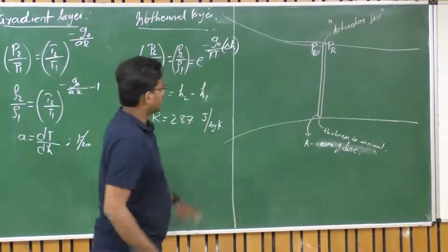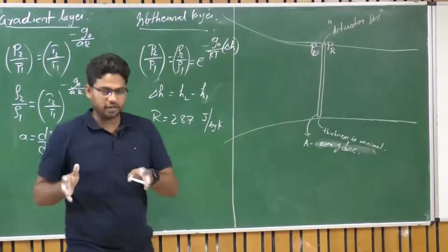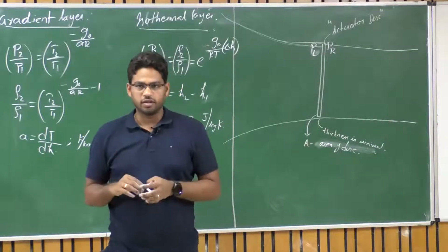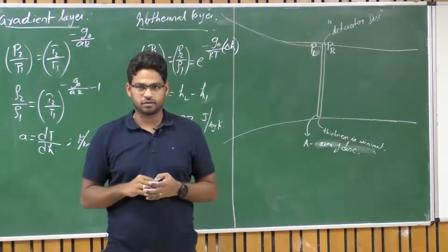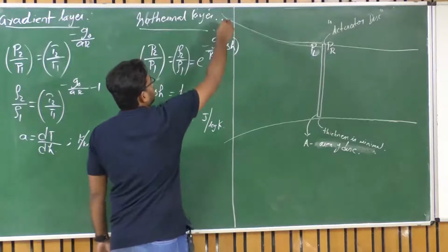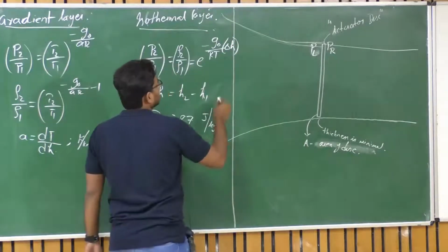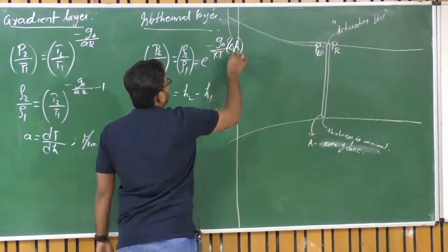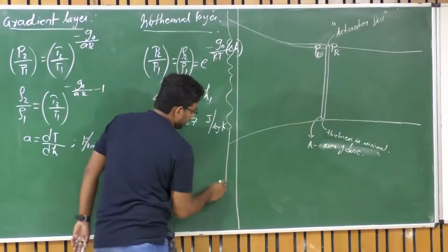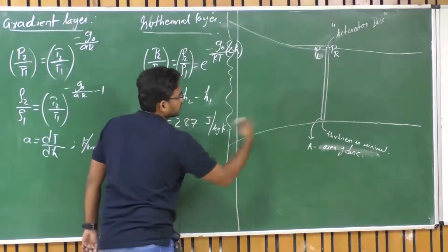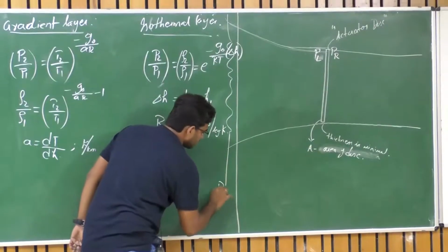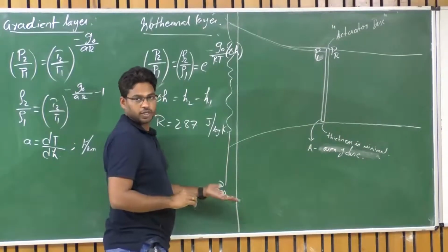So let's now first look at far ahead. Let us say if I place a fan here, somebody who is sitting 100 meters from here, is he going to feel any difference because of this? Definitely no, most likely no, with the ordinary fan that we generally use. So at far ahead, which we call the upstream of this disk, what we have is the atmospheric condition, P infinity, which is 1 atmosphere here.